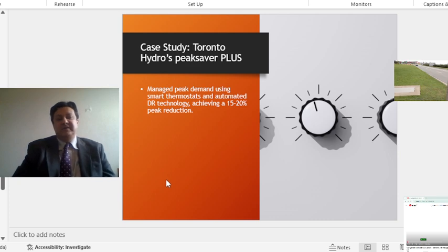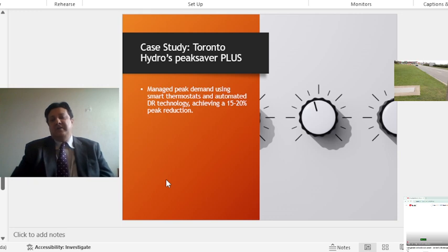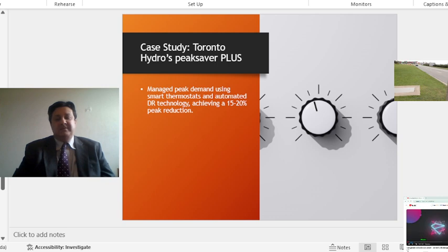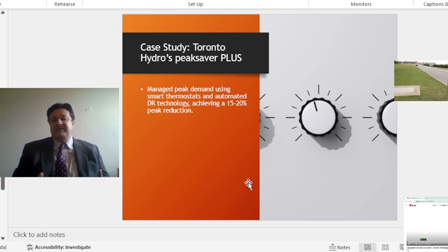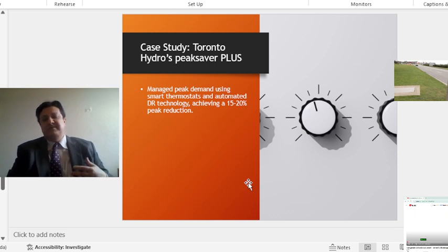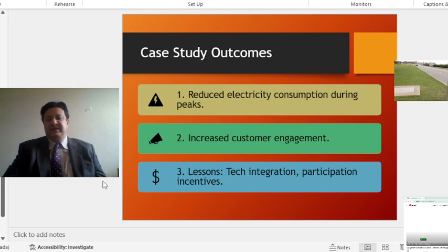Then I would like to share with you a case study of the Toronto Hydro Peak Saver Plus. Let me grab the PowerPoint presentation, because in the next session, hopefully I'll be talking more about the case study. The Toronto Hydro Peak Saver Plus program manages peak demands using smart thermostats and automated DR technologies, achieving a 15 to 20% peak reduction. I have a separate PDF file. We can talk about it.